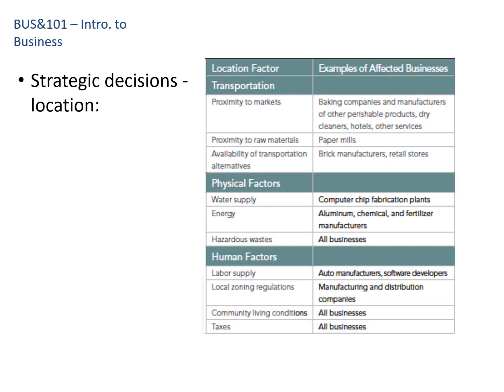So one thing about some strategic decisions about manufacturing, one is location. So where should we place our factory? One way to think about it is, where is the bulk of the transportation taking place? Is it bringing raw material to my factory? If I have a type of business, say a sawmill, where I'm bringing lots of trucks of logs into my business, and that gets manufactured down to a smaller volume of product that then gets shipped to end users, I might want to have my sawmill near the forest. So I'm minimizing the transportation of the bulky, large raw material to my factory.